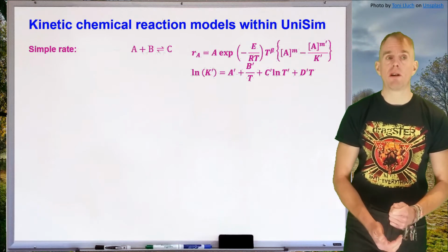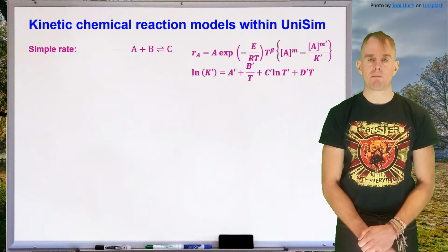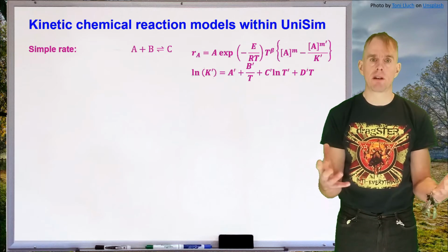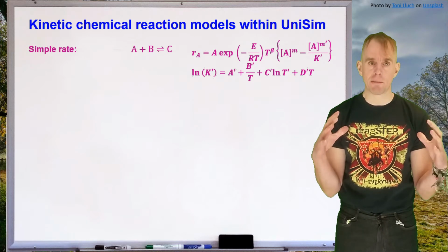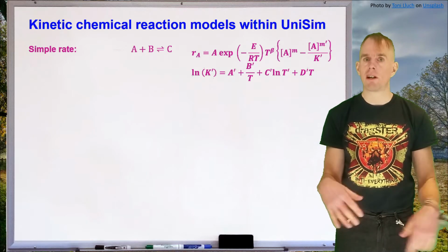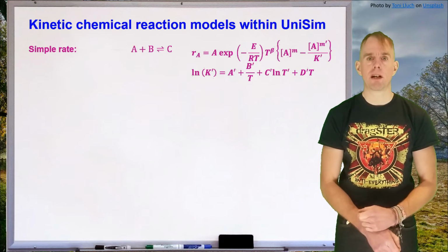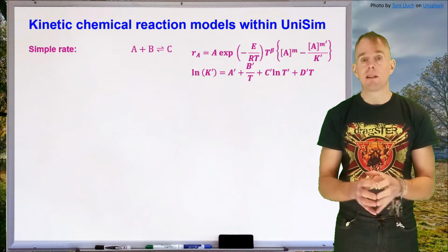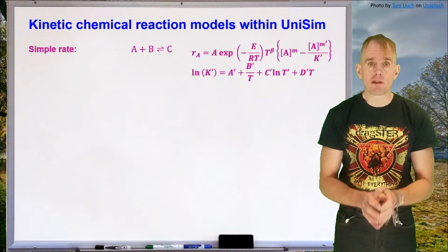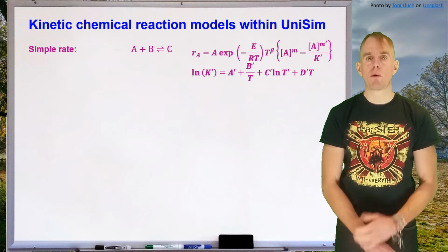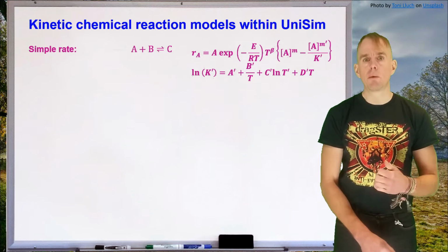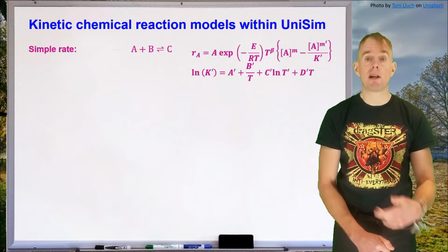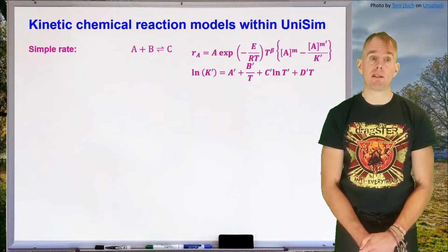If you're doing unit design, you need more information, because if you're producing the mechanical design of a physical reaction system, then you need to know sizing, something about residence times, you need to know temperature profiles, you'll need to know rate data in order to design that. And so if you use the more complex reaction models, you will need to know a good degree of rate data, which may or may not be straightforward to find.